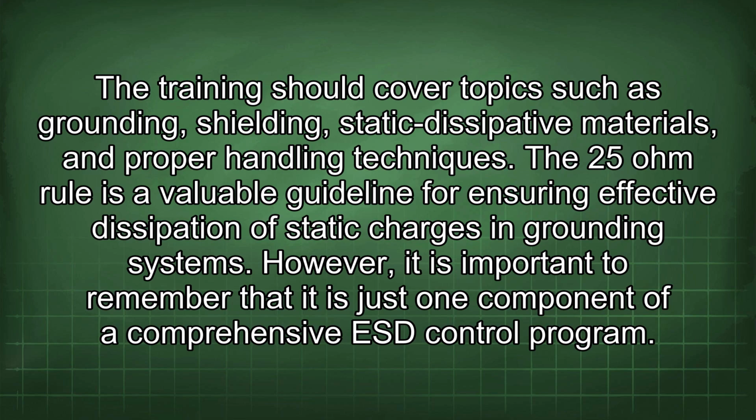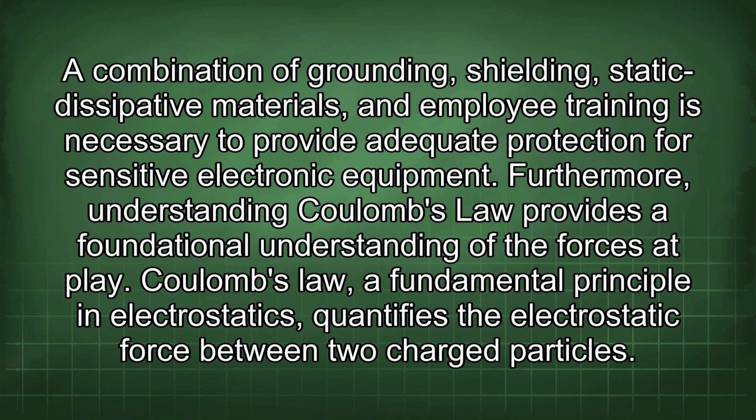The 25 ohm rule is a valuable guideline for ensuring the effective dissipation of static charges in grounding systems. However, it is important to remember that it is just one component of a comprehensive ESD control program. A combination of grounding, shielding, static dissipative materials, and employee training is necessary to provide adequate protection for sensitive electronic equipment. Furthermore, understanding Coulomb's law provides a foundational understanding of the forces at play.